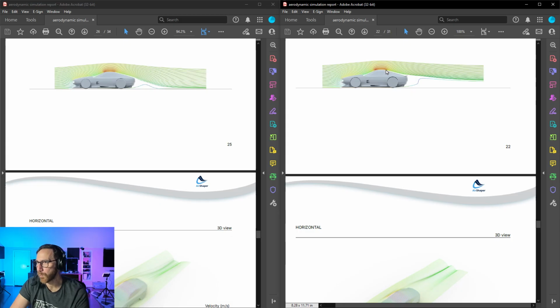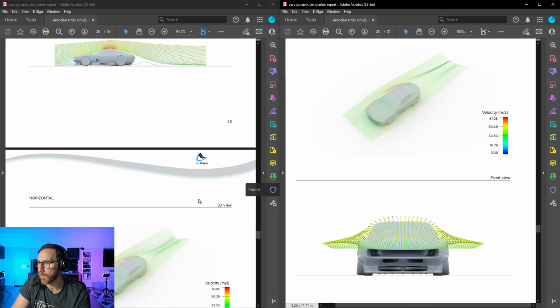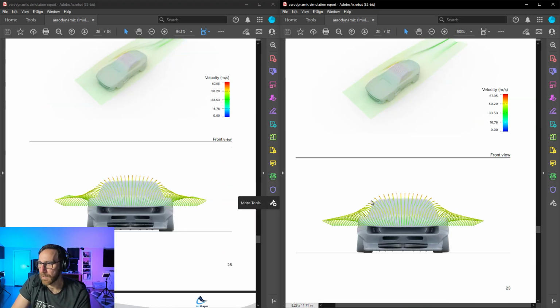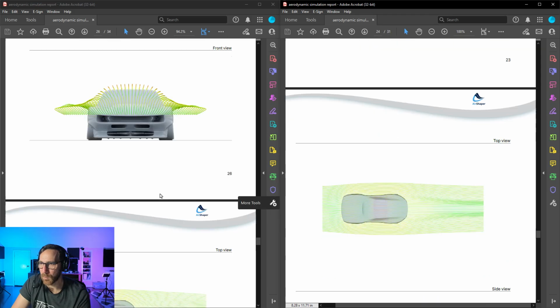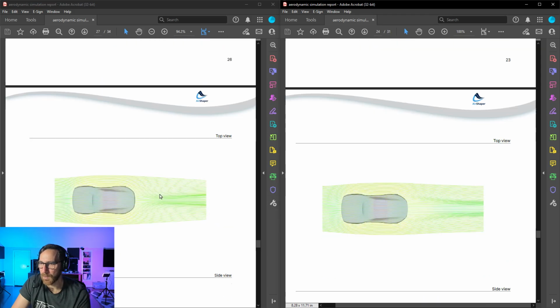But once again, if we put a tiny lip at the top of the roof at the beginning of that glass, and then maybe had a spoiler a bit higher up, potentially we could get some more downforce out of it. But I wouldn't do that without making changes to the front as well, because right now the car is fairly balanced aerodynamically. And then again, when we're looking at these horizontal plots, really what I'm looking at here is what's happening after the vehicle.